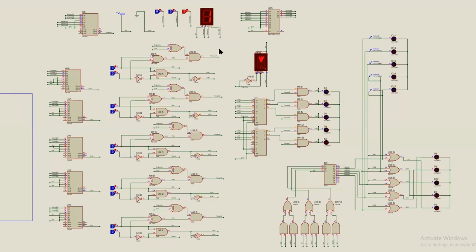Now, let us reverse the conditions where the elevator is on the 5th floor, where no button is pressed. By default, it shows down. However, if the furthest point from 5 is, suppose, 2, the elevator will go from 5 to 2 and it will stop on 2. If the intermediate floors 4 and 3 want to go downwards, it will stop at 4 and 3 because the lift is already going downwards. But if, with the elevator going downwards, 4 and 3 want to go upwards, it will be ignored, as can be seen here.